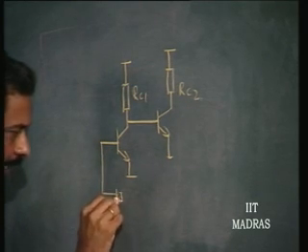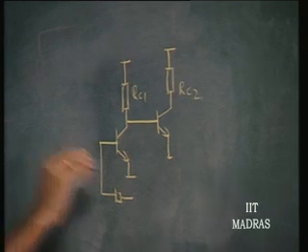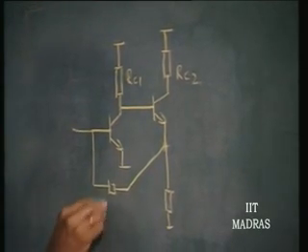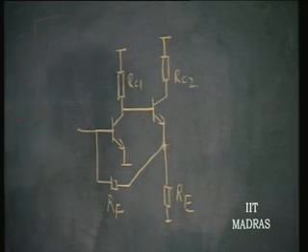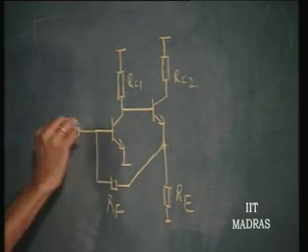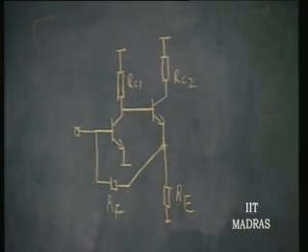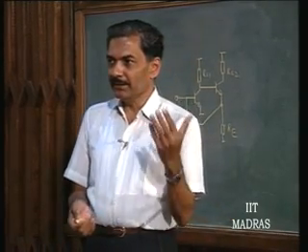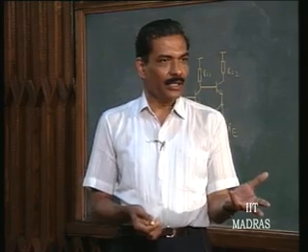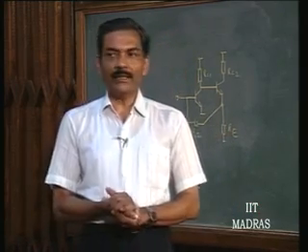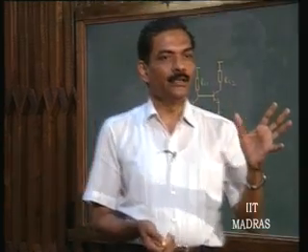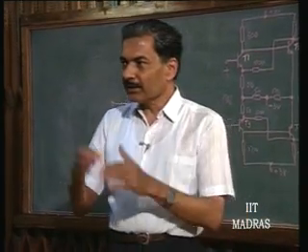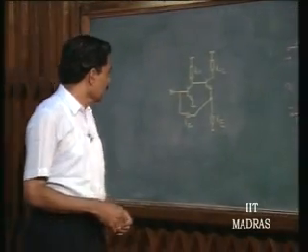It will be shunt at the input and series at the output. So, you have the same thing, RF, RE, but put this way. This should result in what? An ideal current controlled current source. The parameters to be used here for analysis are G parameters. G parameters simply add, and the modified parameter is going to be the H parameter, and it is H21 which gets stabilized or becomes wideband, and all the other H parameters will go towards 0 by the extent of the loop gain. So, all those things remain the same, and obviously what will be the gain?